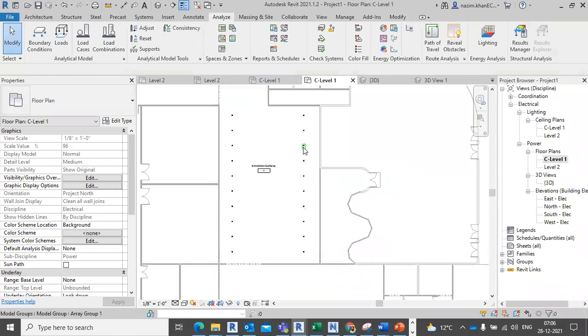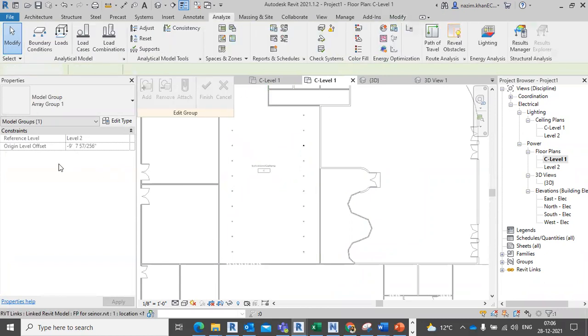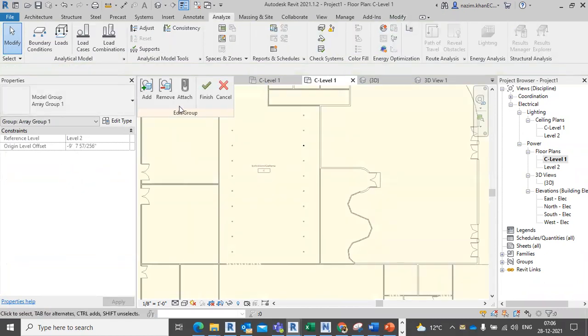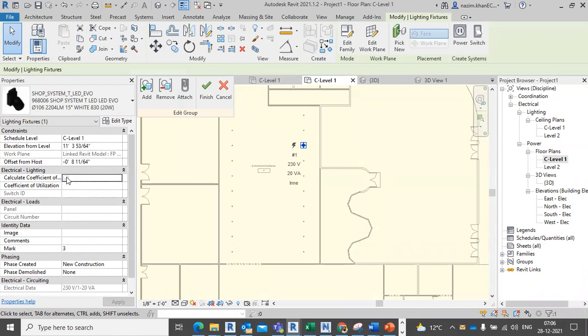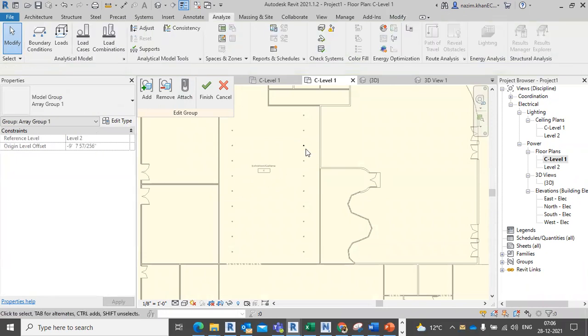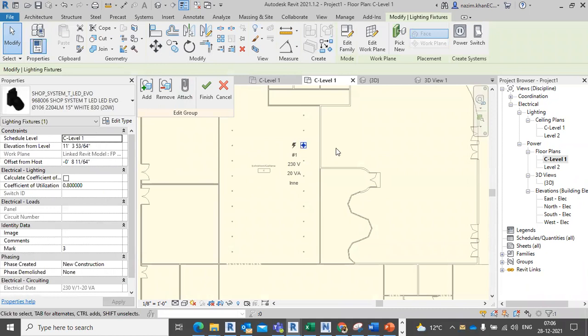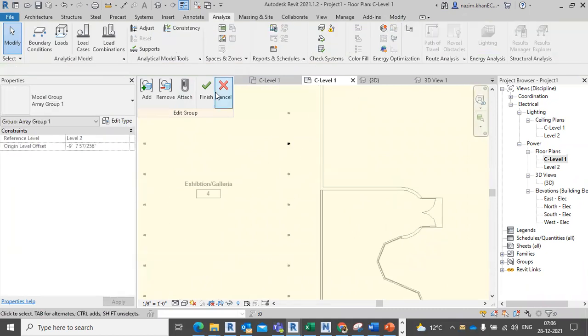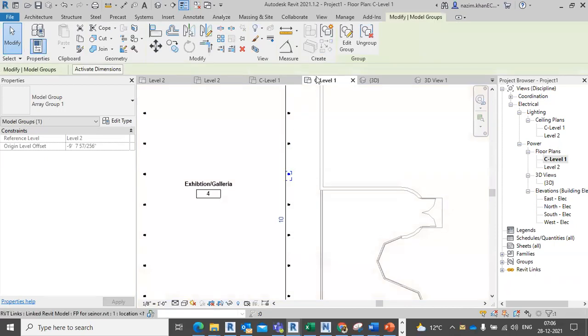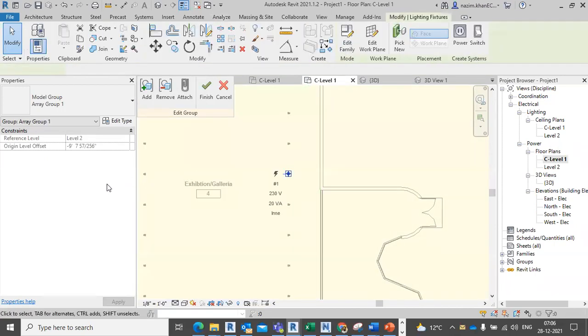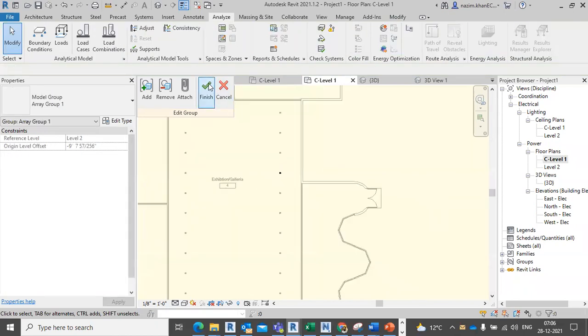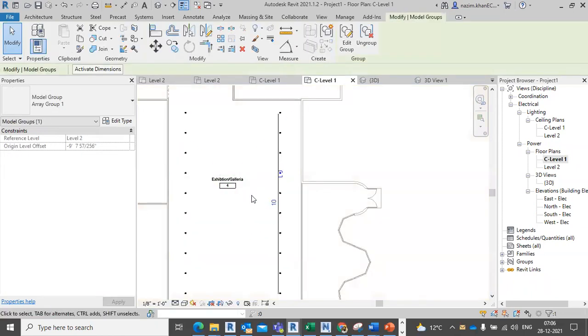The reason being that the lighting that we have installed, I'll just go to edit group. The lighting that we've installed, they have an issue. The issue is that there's no coefficient of utilization. So we'll just put 0.8 generally. Oh, this is the case, and we'll just take. We'll check for other also. Okay. Now let's see. Now we are getting somewhere around.